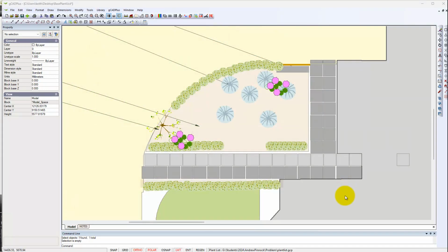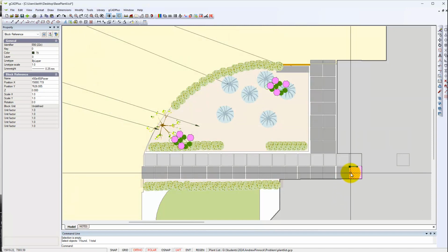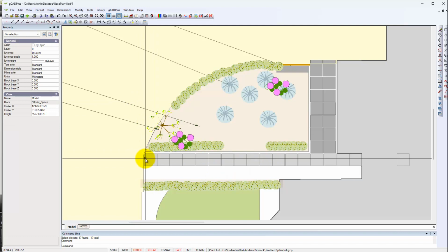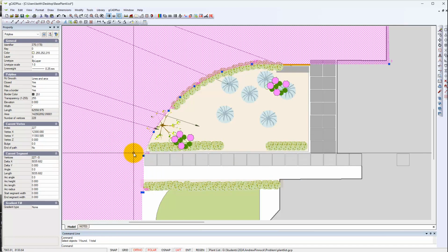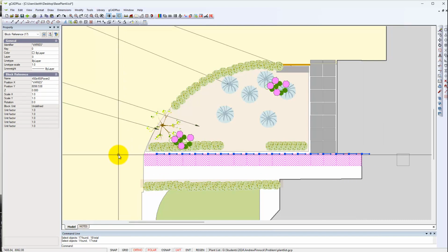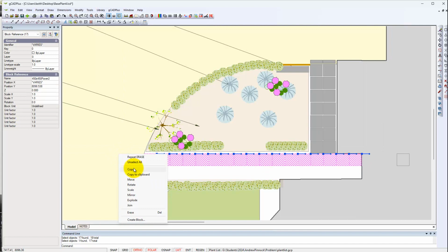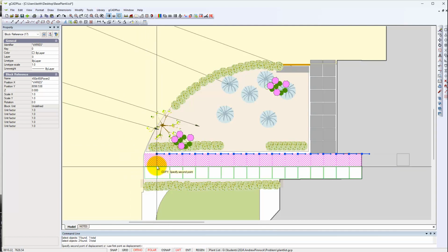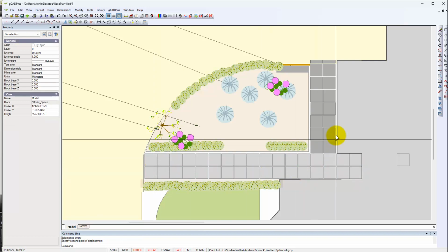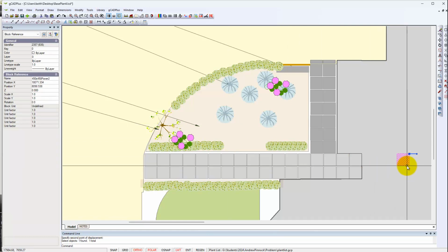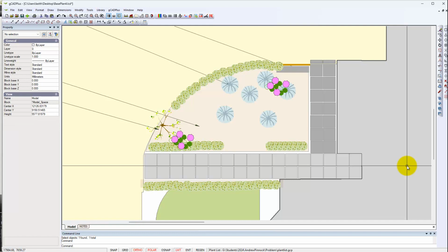And we can use these techniques to build up content really quite quickly. Let's remove that block, and we want to select that group that we've just used. So I'll shift key down and then copy, and remember that polar is on, so we can come down and just copy the whole group, and we can do the same through here. So I hope that helps show the value of the step size, and going to options is pretty important.